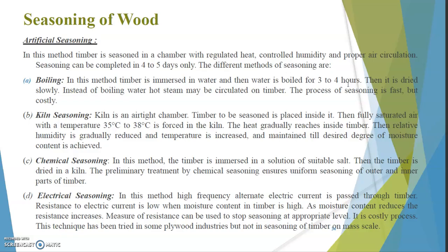So now the ordinary water which is filled inside the wooden cells can be easily dried out with your air recycle, air flow. Right, so that is the purpose why people are immersing it into the water. Don't think in other sense, right? So don't think contradictorily. We need to reduce the water, but still they are asking us to immerse it into the water. How will that happen? It's not that. By immersing it into the water, the exchange of cell water of wood and the ordinary water